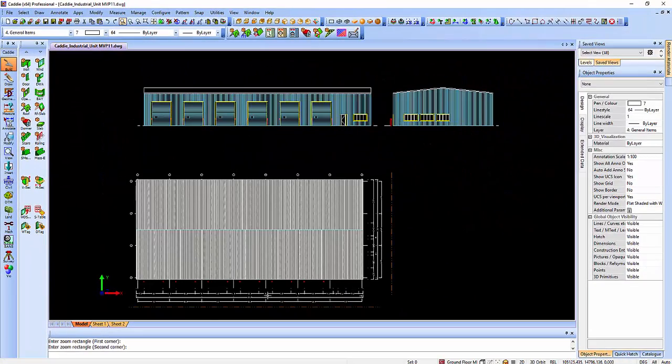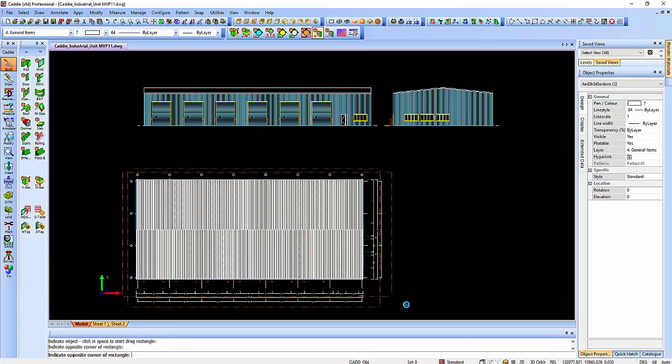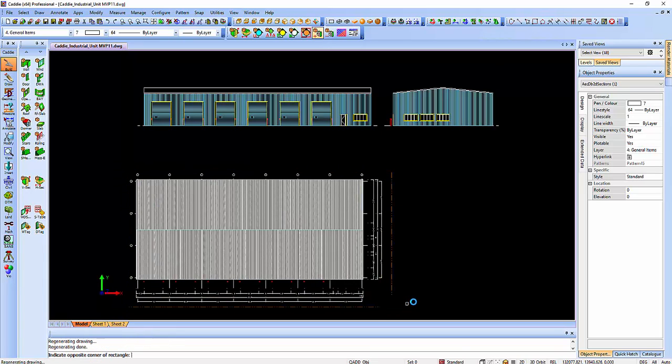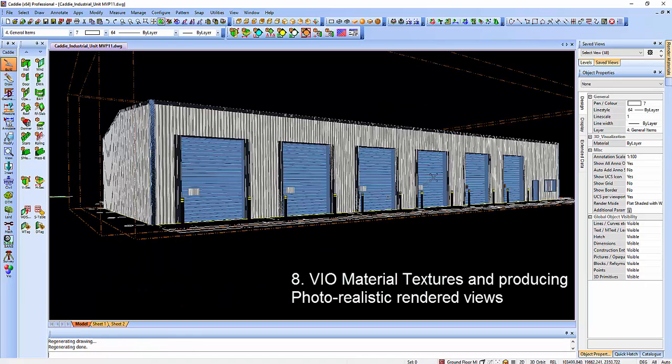Now to introduce the trim panels onto our elevations, we just simply select the section and then say add to all sections. Those other objects I can just drag over the whole of the building and it will just automatically add those to it. So having generated our plan and elevations, we can now look to our 3D model. Roller shutter doors, bollards and so on.